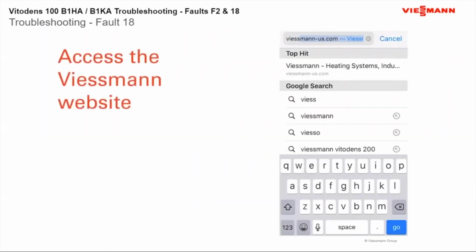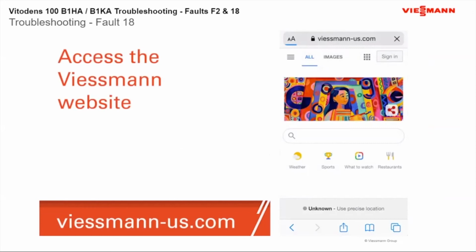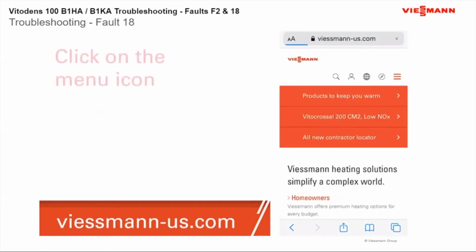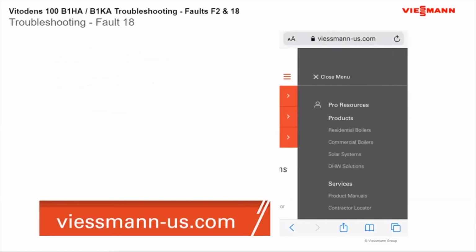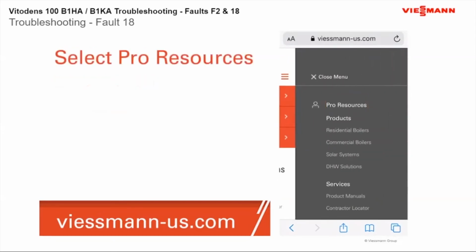Same thing on the fault code checker. You have to put in 18, not an F18, because in the manual, it's under 18 fault, not F18.